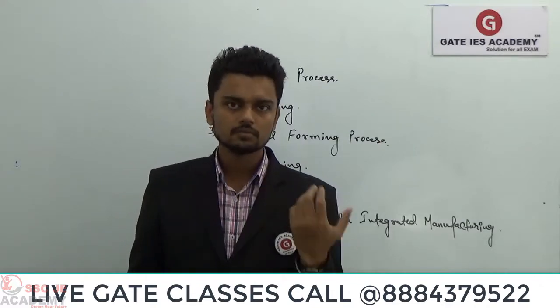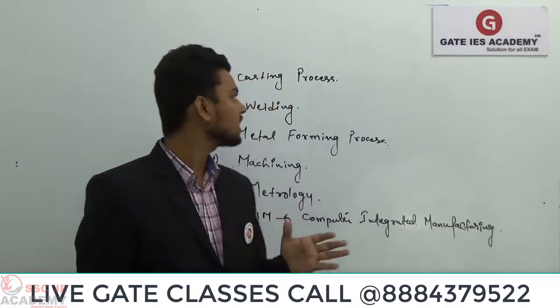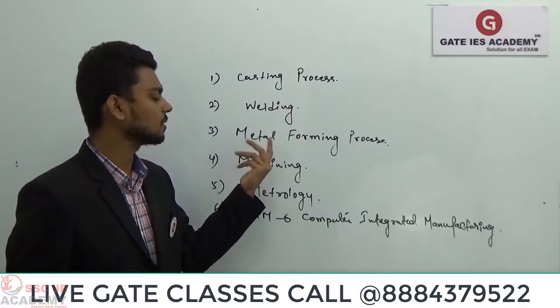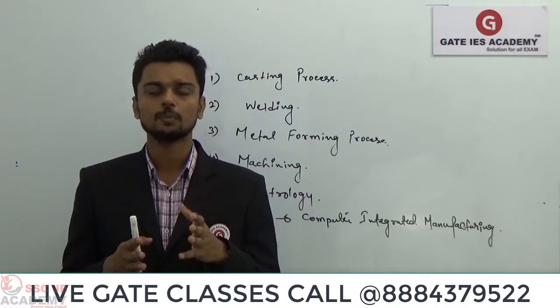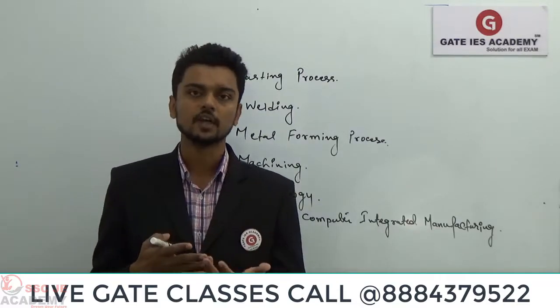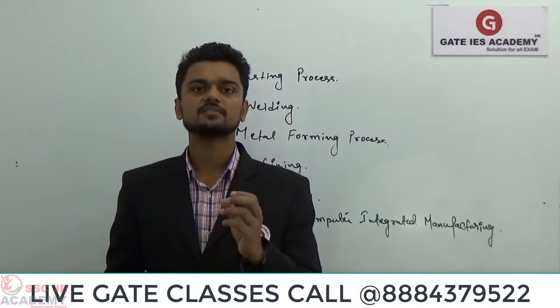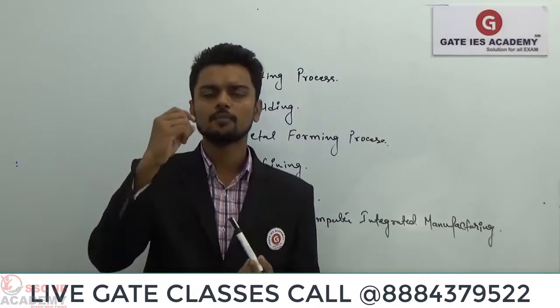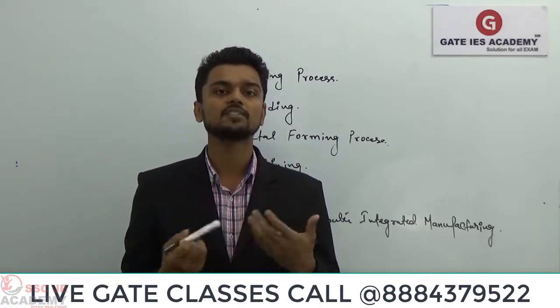Obviously that cylinder requires very good surface finish, and we are not getting that with the casting process or some metal forming process. But for that cylinder, we'll have to make the good surface finish. So what we will do is, we will remove that extra layer of material from the component in order to get the required surface finish.